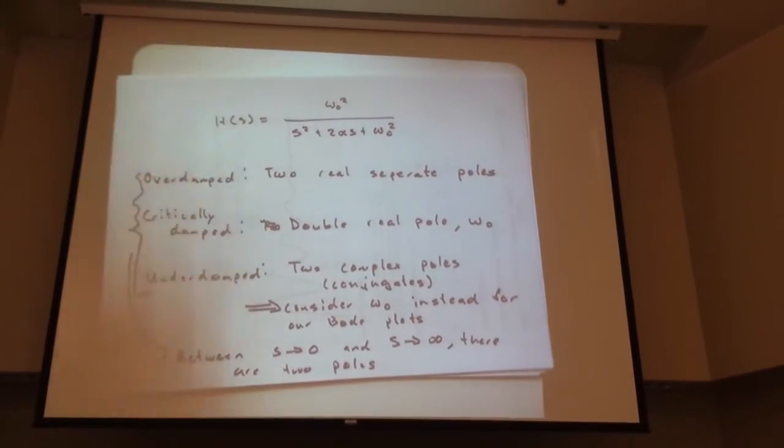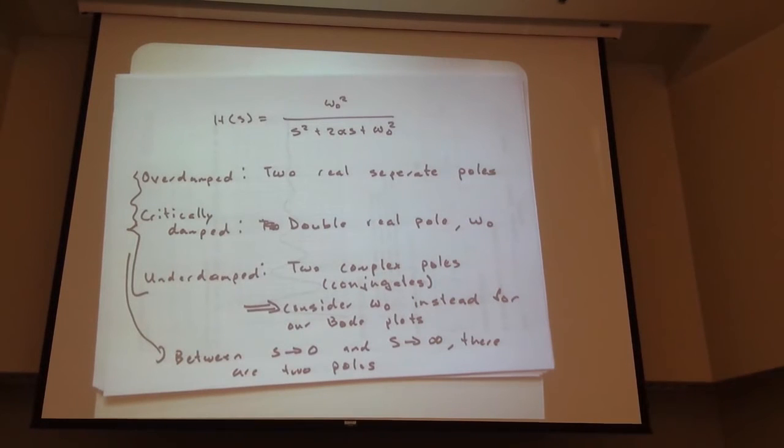Any other questions? Could this problem be solved by two cascaded second order circuits, each with minus 3 dB? Yes, sure. Or minus 2 and minus 4. I mean, the advantage of minus 3 is they're both the same. And less work is always better.